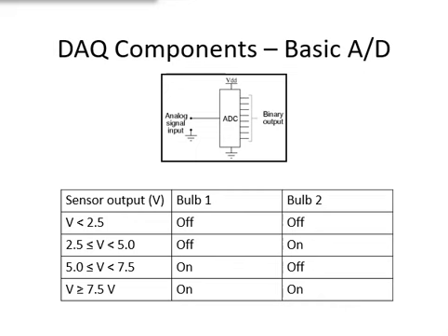Similarly, the output of the transducer could be represented by two light bulbs. There are four possible states for the pair of light bulbs, as shown in the slide. With two light bulbs, the transducer output is now represented more accurately in digital form than with a single light bulb. This light bulb device represents a primitive form of analog to digital converter. The single light bulb device is a 1-bit AD converter and the two light bulb device is a 2-bit AD converter. A bit has two possible states, on or off. Inside a computer, flip-flops instead of light bulbs are used to represent this state.